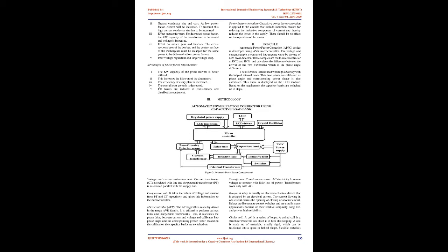Disadvantages of low power factor. 1. Large line losses. Line losses are proportional to the square of current. Therefore, the larger the current, the greater are the line losses. 2. Greater conductor size and cost. At low power factor, current will be increased. To transmit this high current, conductor size has to be increased.